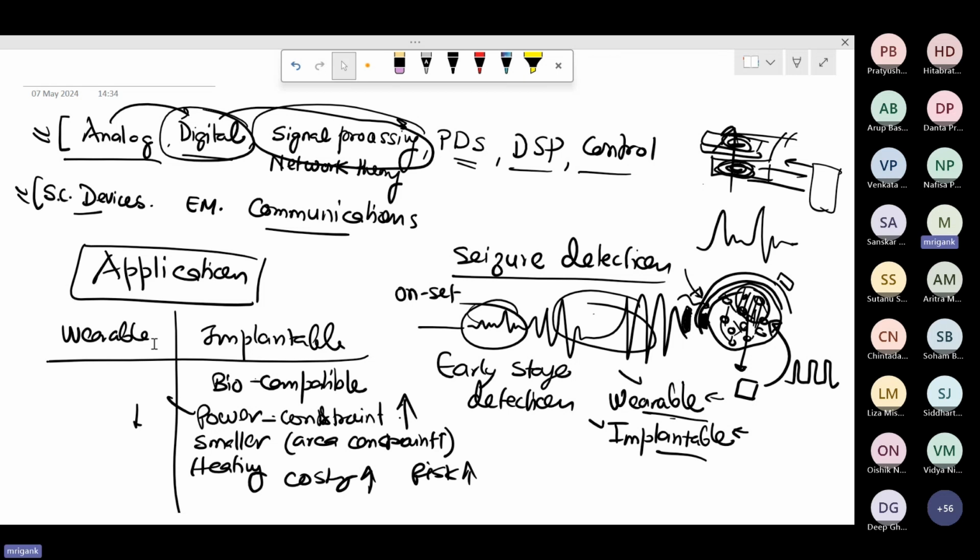So basic operations like what is amplitude, peak to peak amplitude under normal condition, under phasor condition, what is the frequency content of the signal, and how often does it come. You need to study the signal before we implement the signal processing scheme and try to implement it on the circuits.